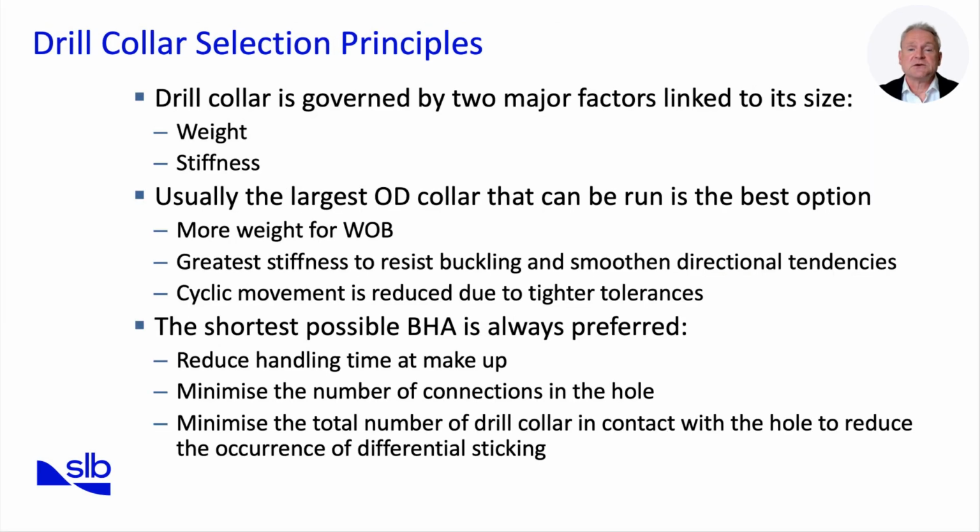Drill collar selection is critical because it directly affects weight on bit, directional control, and buckling resistance. Two key factors govern drill collar performance: weight and stiffness. Usually, the largest outer diameter (OD) collar that can be safely run is the best choice.